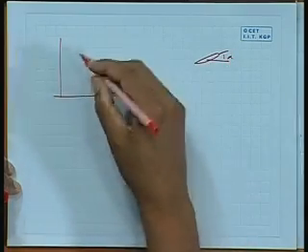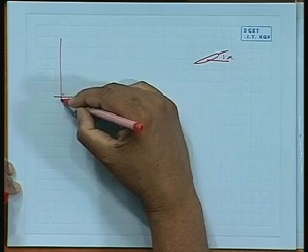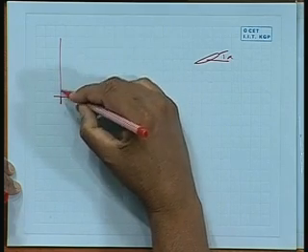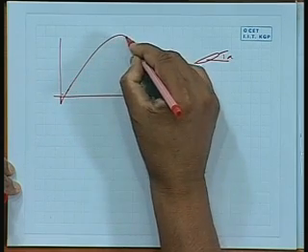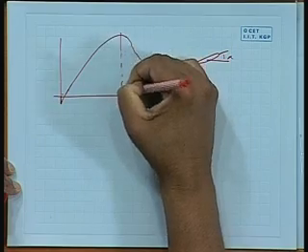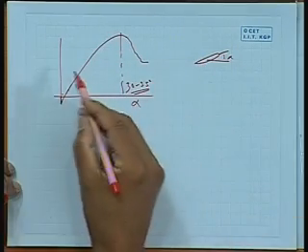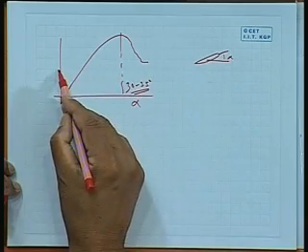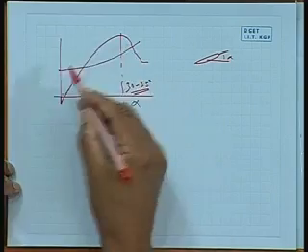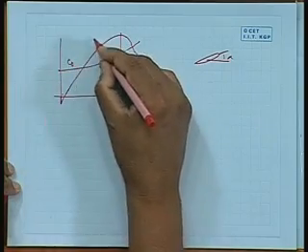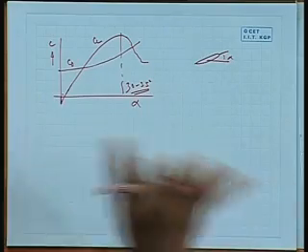It turns out that CL and CD, one of them CL, normally need not be always 0, but somewhere here, let us say, it goes up there and then at some point it stalls. This is up to normally around 30 to 35 degrees for most of the common sections, and CD initially starts a little bit high, and then of course it still goes up, and there is CL by CD. This may be CD, this may be CL. This is actually the coefficient, and this is the angle. Typically it looks like that.